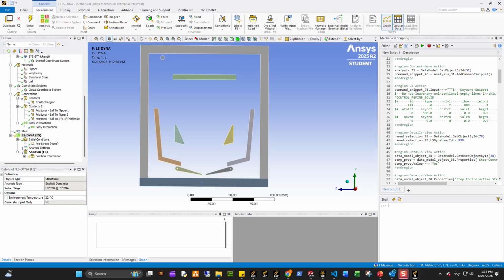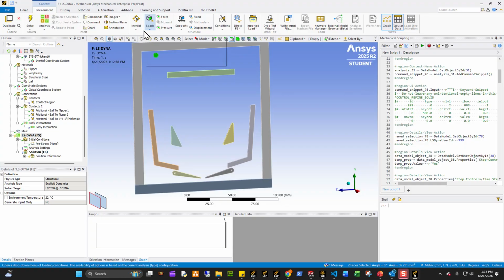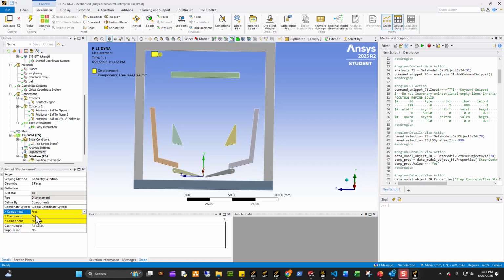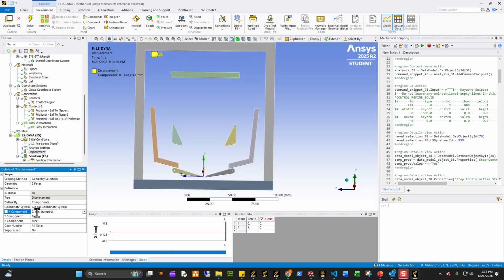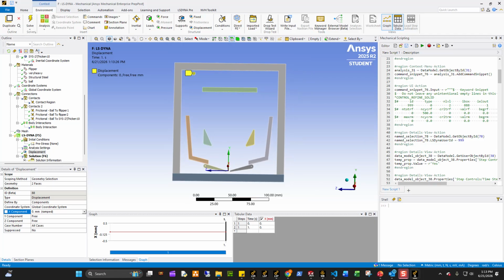The first thing we wanted to set up is that we want to make sure the ball is only allowed to move in the YZ plane, which means I'm gonna essentially constrain any kind of out of plane movement. I'm gonna set this to 0, and that basically constrains the ball so it can only move in that direction. And what I also like to do is to create a rigid body constraint for everything else, right?